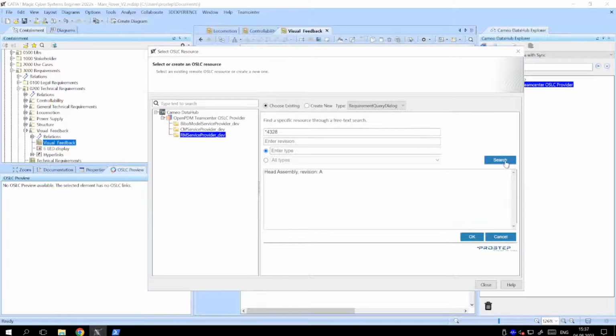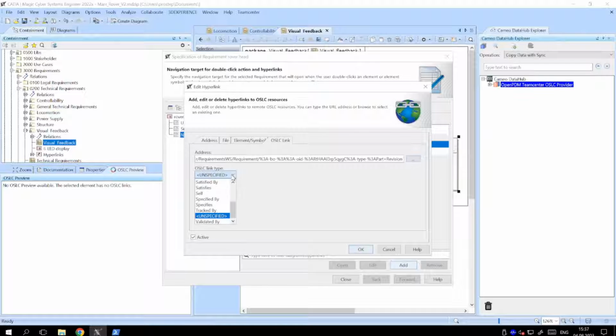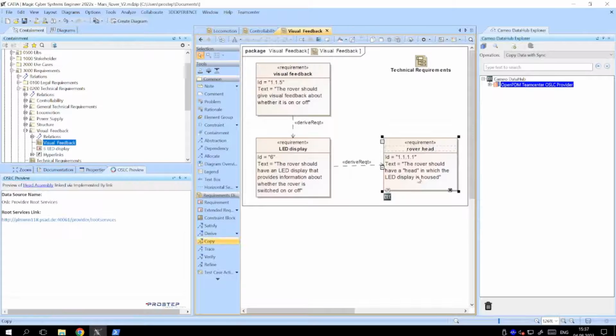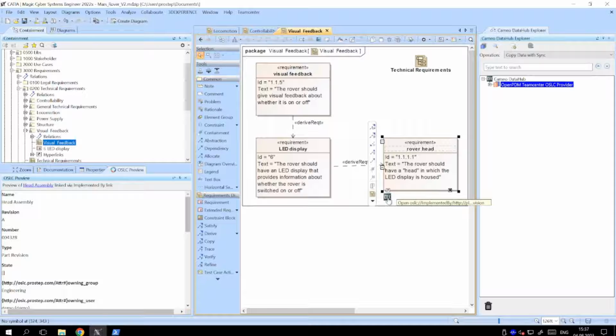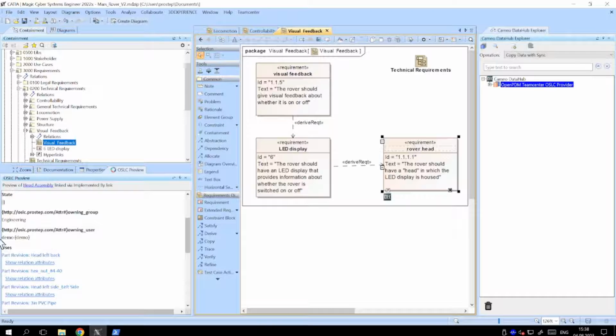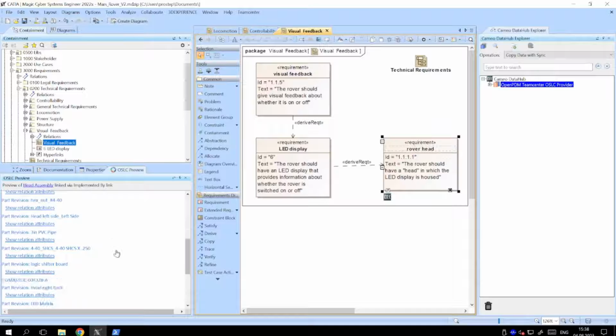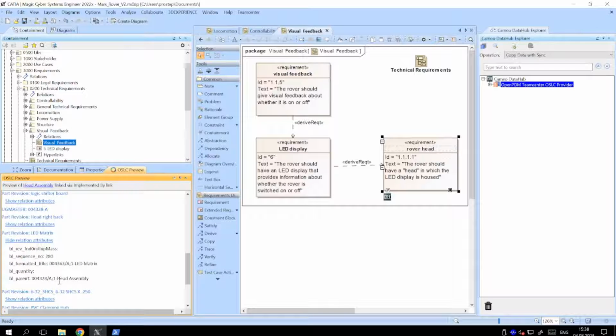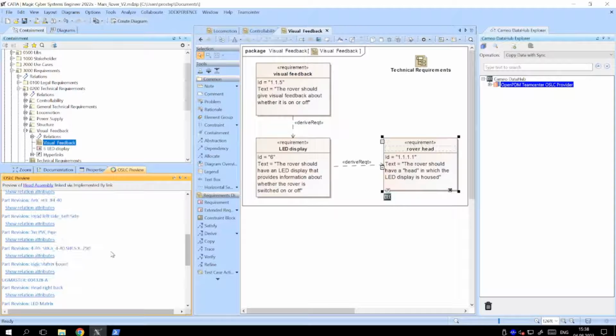This is what's called a delegated UI in OSLC. So this little HTML frame is actually provided by the OSLC bridge, and then shown here. Now you can customize what those are to support really different use cases as well. So if you want to interact with other data in the system, you can create other delegated UIs to handle that. So now that that's created, you see the little DH link, you see the OSLC preview, it's got a bunch of attributes. It also has different places where you can select, click through, and hyperlinks that might be able to provide files as well.